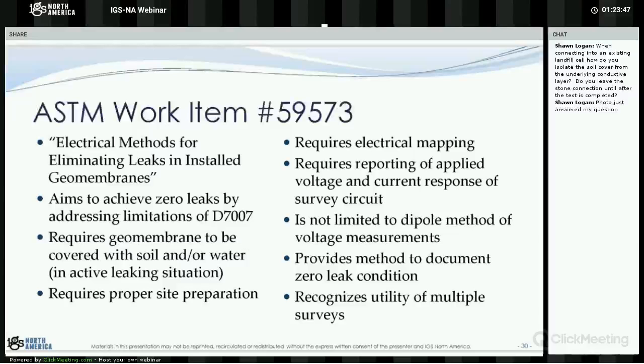And I can tell you without a doubt, there are such tiny, tiny holes that I have found dozens and dozens of that I never would have found if I hadn't done the GPS-based mapping. Because in the map, we can see signals that are so incredibly small that you won't see them when you're just looking at the voltage because it doesn't give you a strong polarity sign change. You can only see them because you know the pattern that a leak is supposed to make in the data.